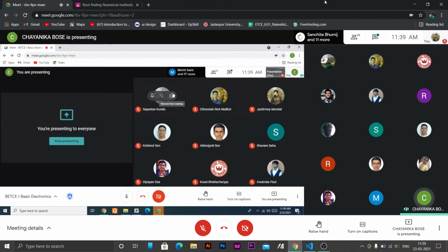The control signal we are giving, suppose it is like a square pulse. When it is high positive the switch is on, and when it is a negative value the switch is off. Our pulse varies from say plus V to minus V. That is our control signal. The switch must follow that. So when abruptly our applied switching voltage becomes minus V, the junction should be reverse biased for the diode.